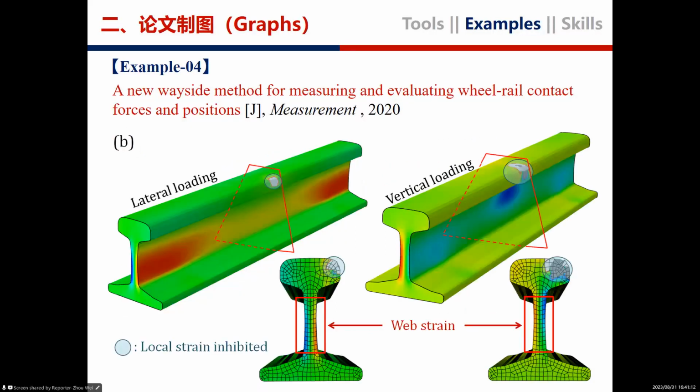Here to show the strain distribution when the rail track is subjected to deviated vertical loading and lateral loading at the wheel flange, we picked the whole model with contour strain plots and a subplot in front view of its sectional vertical strain so that we can see clearly the strain difference at the two web sides. These skills can help readers better understand the effect of deviated load-induced bending on structural strain and the stress of real web size. To achieve this, we need to get good pictures in finite element analysis software and well organize them in PowerPoint.